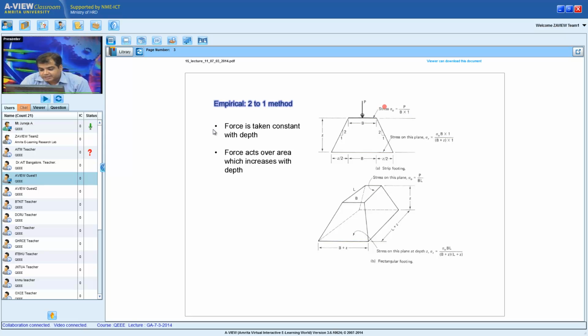Over here we have written stress. Now I would like to emphasize that this word is incorrect. You don't apply stress over the ground or over any material. What you apply is pressure. Stress is something which is manifested or developed within the system or within the ground. So when I apply pressure, I only apply load or pressure, but I don't apply stress.